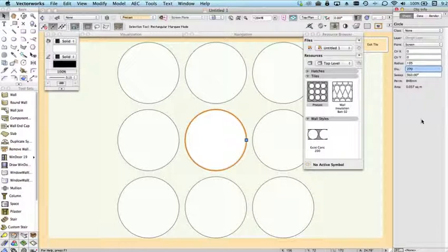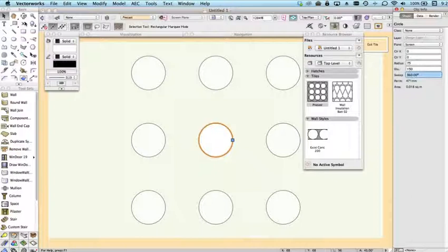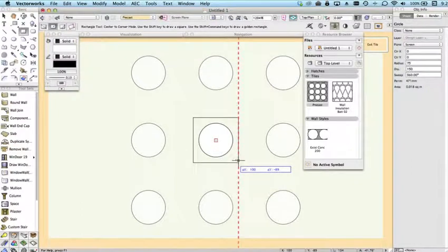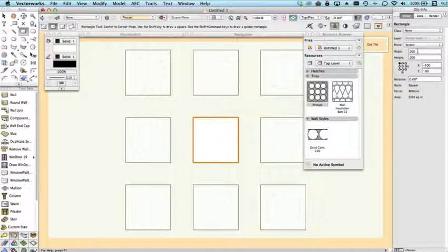So that we can actually precisely create these dimensions, because this is being fitted to the wall, we'll actually set this to what the hole should be. So let's say in a 200 wall you want the hole to be, I don't know, 150. Alright, so the hole's now 150. So what we're going to do is to draw a rectangle from the center, and this rectangle is going to represent however much bigger the wall or the gap you want. So if we make this 100, then essentially we've got a 200 by 200.